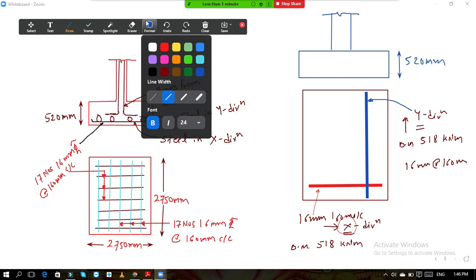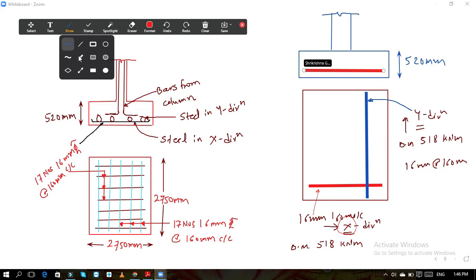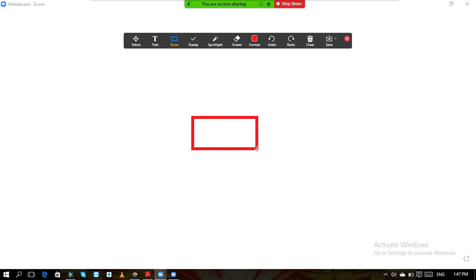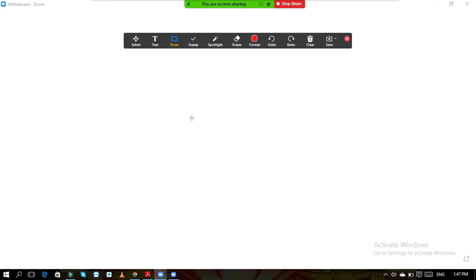Now what will happen? We will provide first the bar in X direction. Okay. So by lifting some clear cover from the bottom and side, we provide this bar over here. This is the same bar which is provided in X direction. Okay. So now, but I will tell you again. So I was explaining you sectional elevation. I think you have understood the plan. Now sectional elevation in this here. This is your depth of the footing.